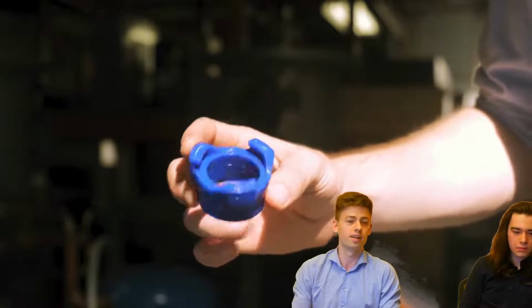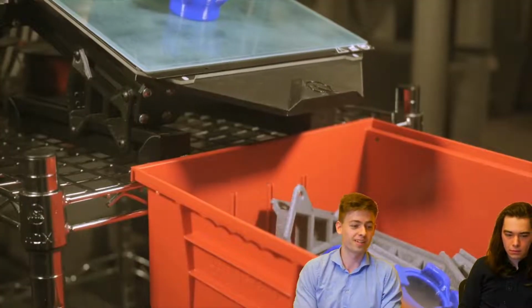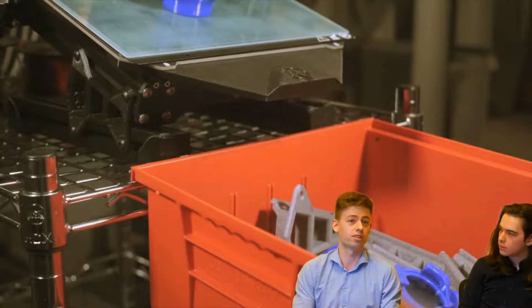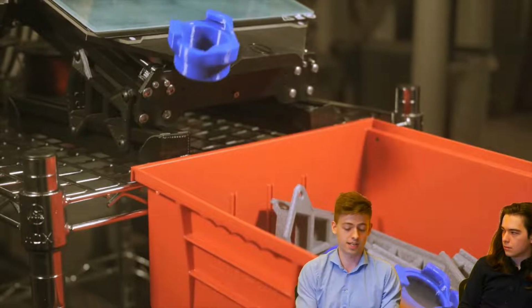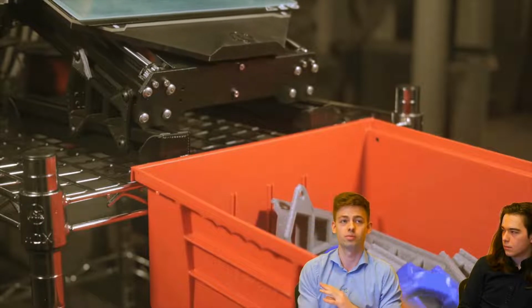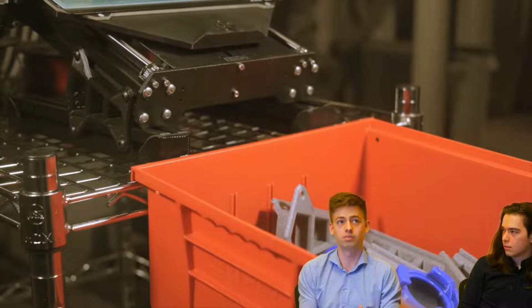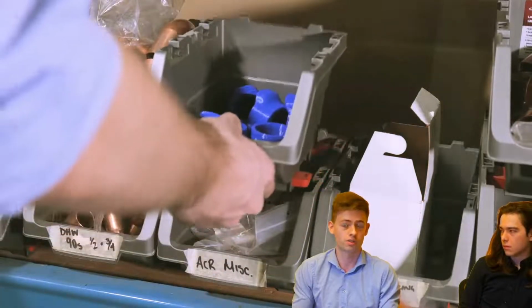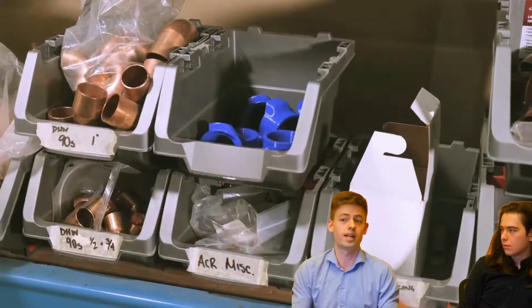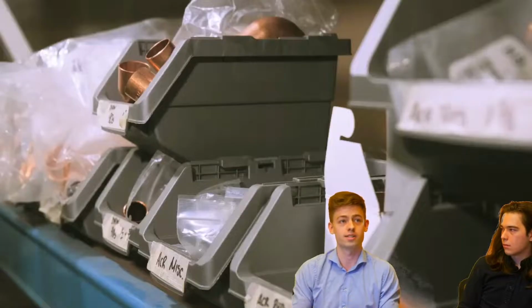Maker's Muse did a good video on this, but you can say that the printers handle the retraction rather than the G-code. Mm-hmm. And then you could have a central G-code that has retraction for any printer, and then you can do temperature offsets for any material or nozzle, and then maybe even an X or Y offset on the model itself. Yeah.